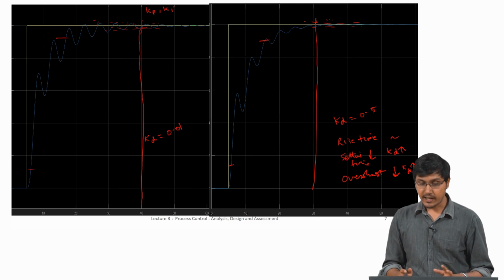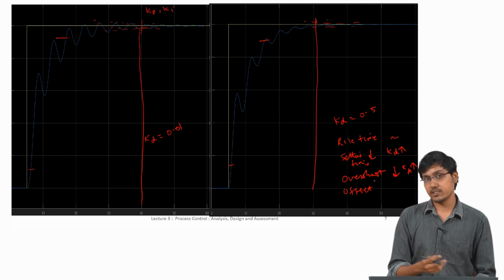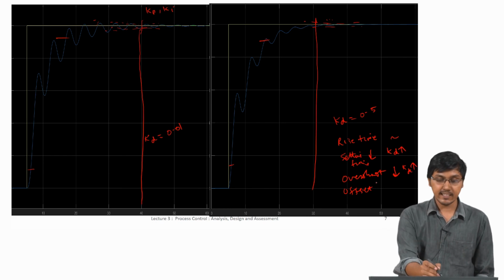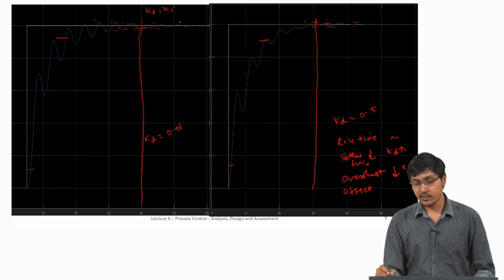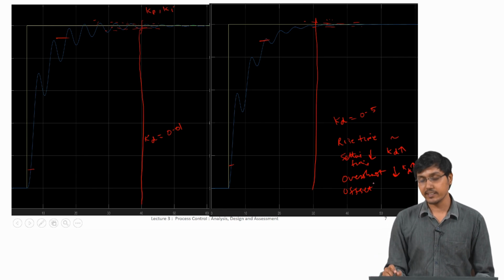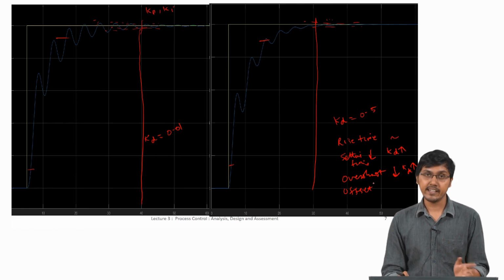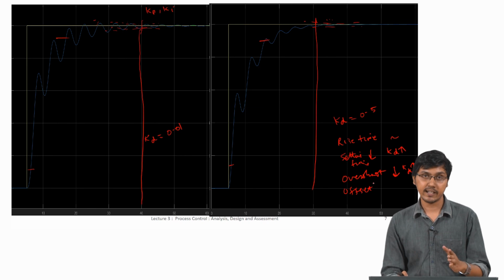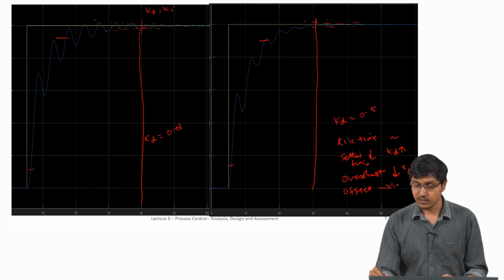And the steady state error value, that is the offset, is not going to have any effect. Whenever you have an integral controller, the offset is 0, so that is why it is not going to affect anything. Even with the proportional and derivative controller without integral action, when you set Ki equal to 0 and use only Kp and Kd, you will see that the final offset, the steady state error value, does not really depend on the Kd. So, here there is no change.